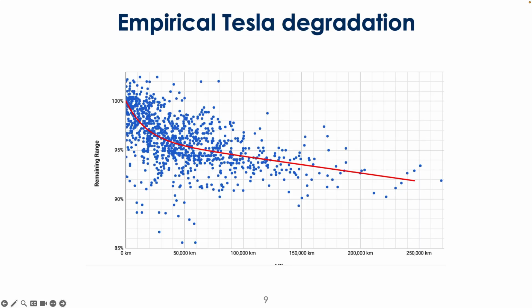That really does speak to the good battery management systems. Surprisingly, folks who were only going to supercharger stations, we were finding that their batteries were not necessarily degrading any faster. But still, I would be hesitant to generalize that without digging into it more. I think in general, it's probably a good idea not to just fast charge all the time.